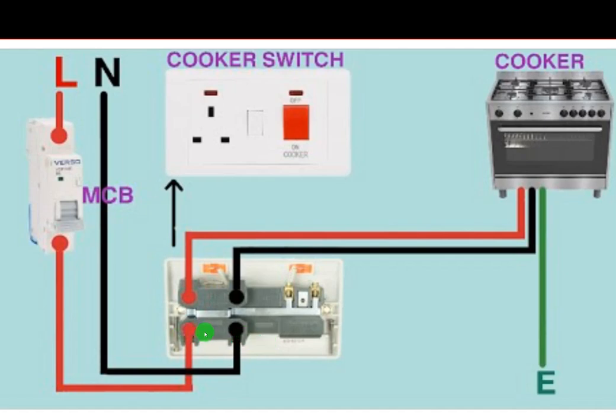Supply comes here, and from here the supply moves to the cooker. You now see that this socket does not go for the cooker. This socket is for a different auxiliary use, for you to use smaller appliances, not for the cooker. Just switch here, the connection here will be connected, then the cooker will get energized. So the connection is at the back, and that is why whenever you purchase this cooker, it does not have a plug. I repeat again, whenever you purchase the cooker, it just has a cord, but it doesn't come with a plug.